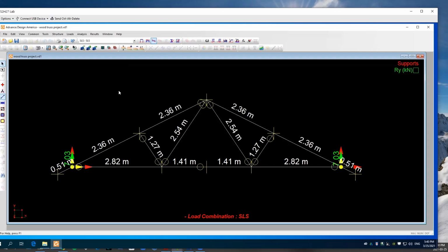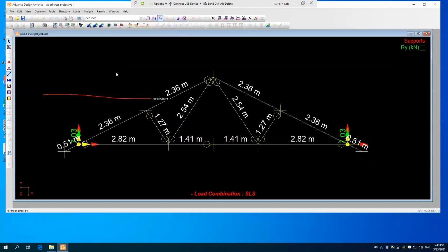And then of course, what I want you to appreciate is that this is already an axial force, so you don't have to worry about tributary width. This is already your axial force, and that's only because your studs are spaced exactly the same as your trusses. So what that means is that if the truss happens to fall exactly in the same location as the stud, here's my truss on the roof, and the stud is right underneath it, well, that's exactly what happens.